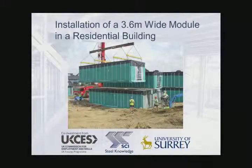Here we see the installation of a 3.6 meter wide module in a residential building, where two modules create one house. And you see here the modules are lifted by a spreader beam at 8 points along the length of the module.